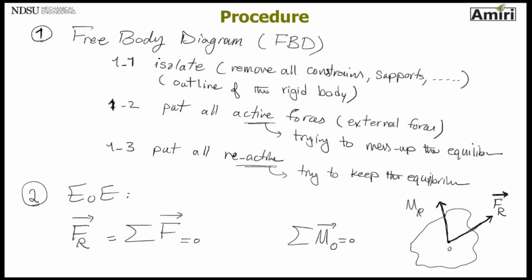Sorry, this is going to be MR, the resultant moment at point O for me, which is this guy right here. So these are my two equations that I need to satisfy. Step 1 is to draw a free body diagram. Step 2 is to satisfy these two equations.